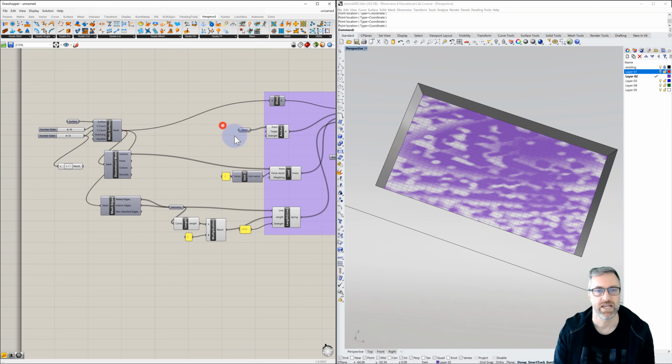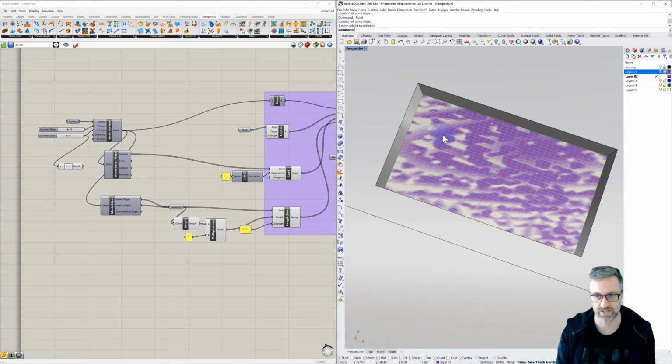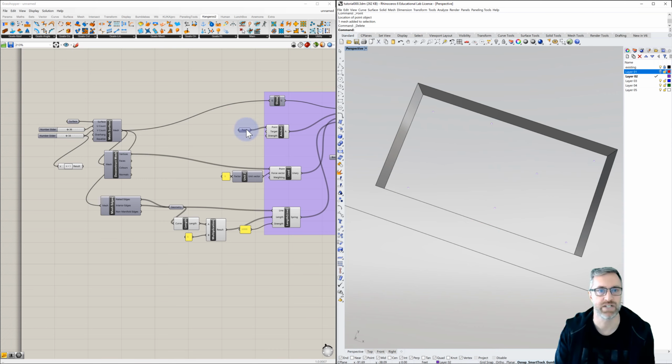We're just going to bake it for a second, put it on the layer that I'm working on. Now what I can do is I can select points, or I can draw points in Rhino. And as long as I have my snap set to vertex, I can choose a set of points. And these points can be set there. Now that I have those, I'm confident that those points match the starting points that are at a vertex on the mesh. I can delete the mesh, because again, that was just a baked surface. But now as I get to anchor, I can set multiple points.